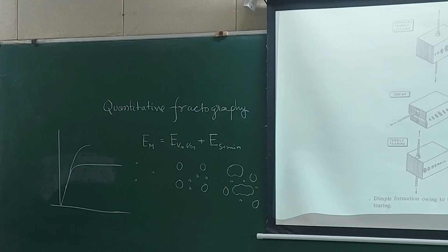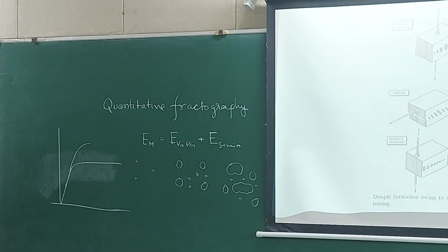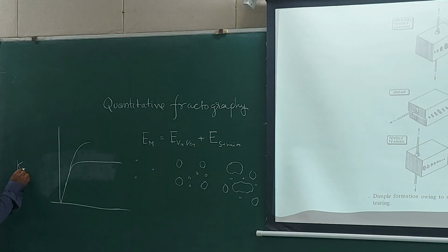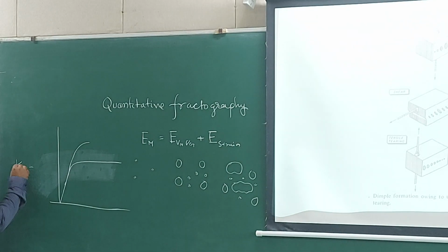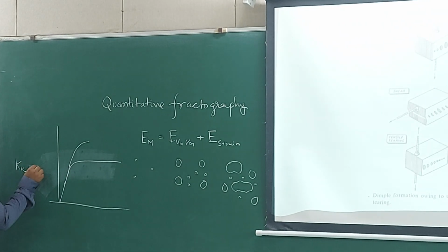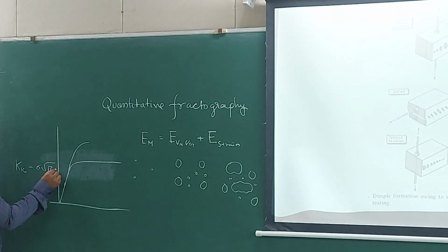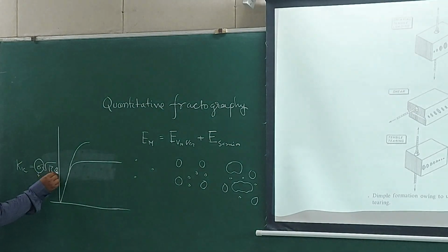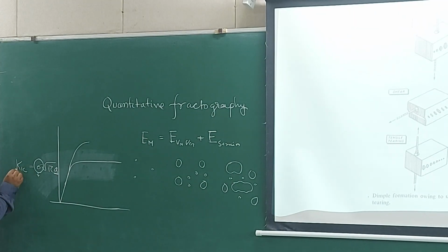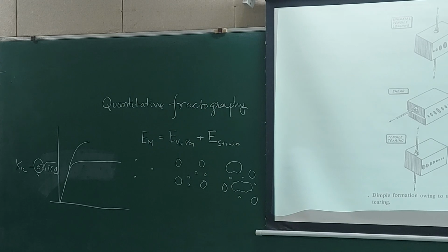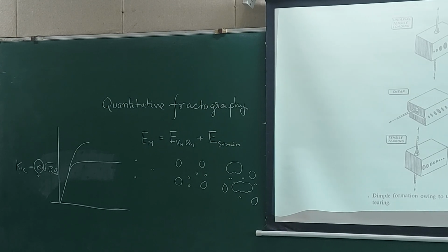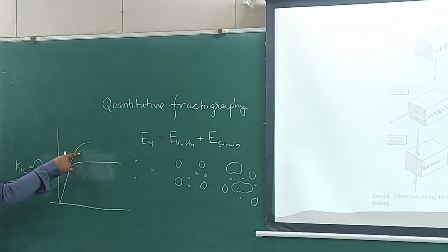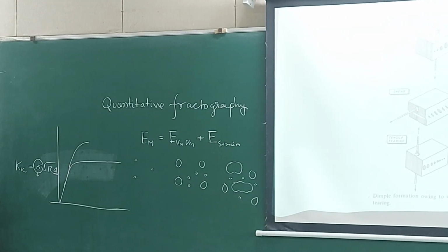So what is the critical crack length? If you look at it with the stress intensity factor, although in a very highly plastic material you shouldn't use K1C, but just for the sake of it, if you calculate this for any given amount of stress, a will be larger if this is larger, and for the ductile material, for this one K1C will be more, or for this one K1C will be more.